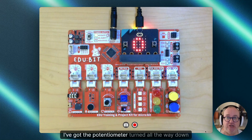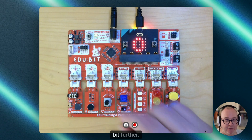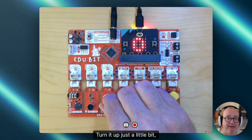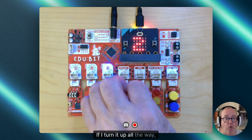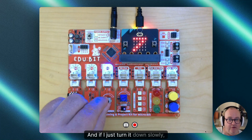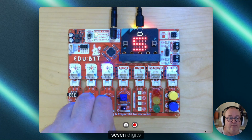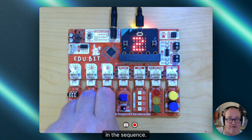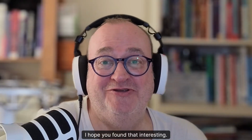I've got the potentiometer turned all the way down again, and you can see I've got a 0 on the microbit. If I turn it up just a little bit, you can see it's changed to the number 2. If I turn it up all the way, we've got the number 7. And if I just turn it down slowly, you can see we can go through all 7 digits in the sequence. Hooray! I hope you found that interesting.